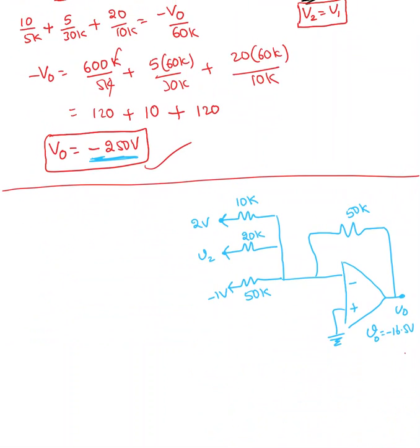Now here is the next example. In this next example, this is also an inverting amplifier, so output is going to be inverted, and it's a summing amplifier. He gave you the V naught value, he's asking us what is V2 in this case. Okay, so we always take this value as V2, this value as V1, and remember current entering here is 0, current entering is also 0. All we know, V1 equal to V2 equal to 0 volts. Okay, that's what we know.